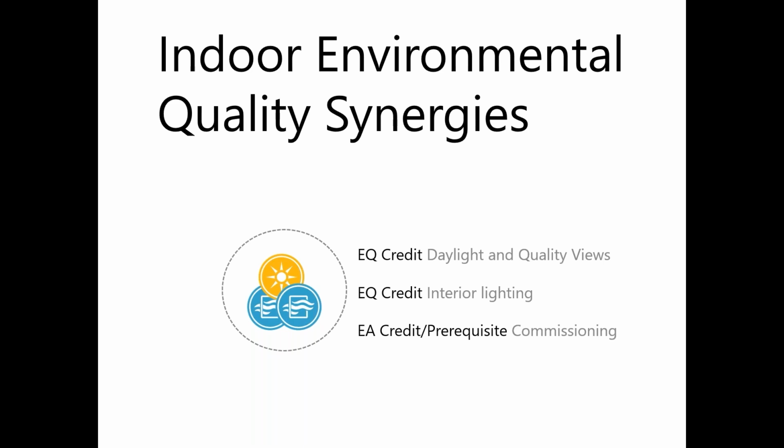So when we talk about synergies, again, we're trying to tie in different technologies and strategies within our project that can help, for lack of a better phrase, kill 2 birds with 1 stone. Maybe we can implement some strategies that help earn some LEED points in multiple areas. So a good synergy, and a common one we see, is this daylight and quality views, where we're bringing in more natural light, giving people that view to the outside.